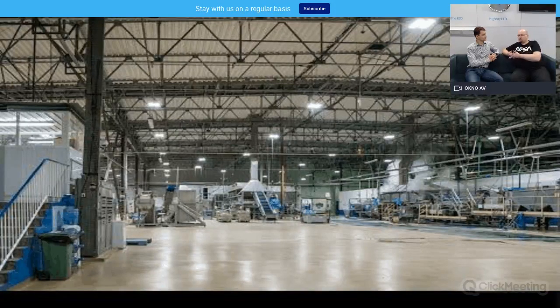So they have to be compatible with cleaning agents. We have to check the chemical compatibility data sheet for the product for this typical client. We also need IP65 minimum, and of course the broadest temperature range possible, with the ability of the product to survive in low and high temperatures. So we saw in the movie that this kind of food processing requires refrigerators and freezing rooms, with temperatures from -5 to +10, or 0 to 10 for refrigeration, and -15 up to -30 for freezing.